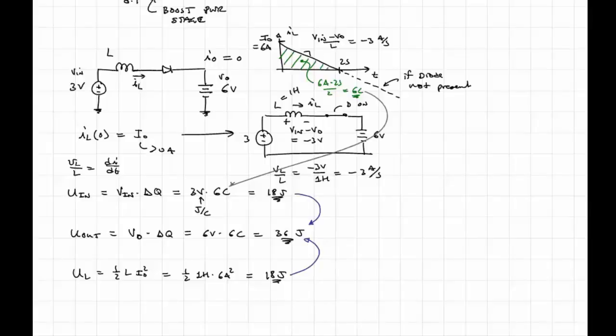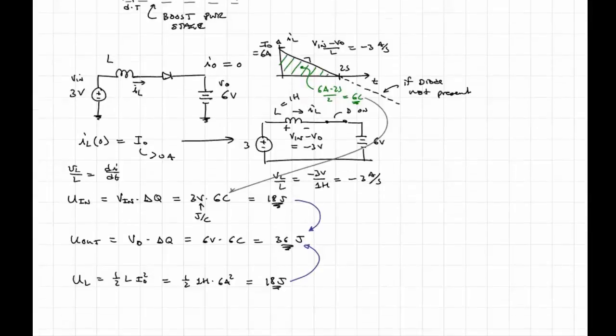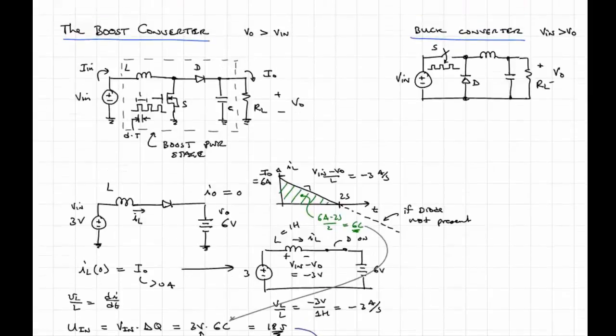And the vehicle for allowing our diode to conduct, and to basically provide a mechanism for charge to flow uphill, if you will, from a lower potential to a higher potential, is the inertia, if you will, of the inductor. Okay? And so this circuit that I've just drawn, with the voltage source, the L, the D diode, and the output battery, is the boost converter minus the switch. So I can go back in here and draw the switch, but I'm going to say S is off.